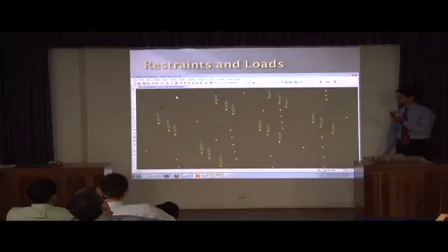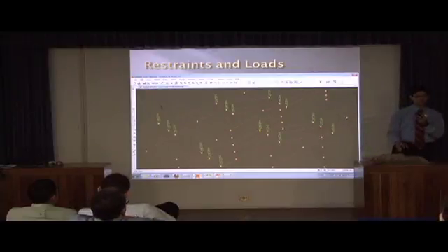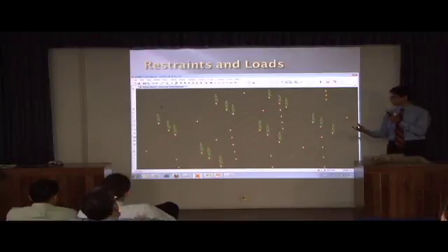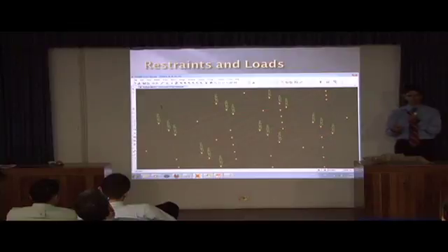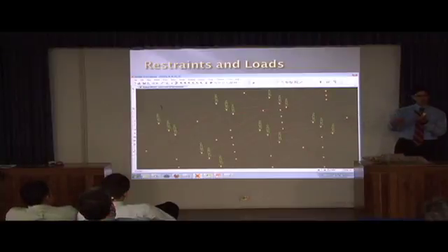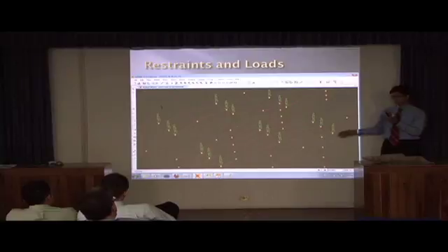Now, referring to loads, we know from reference data the weight of the motor, the engine, and reductor gear. That will be placed in a kind of structure like this. So we have to determine how many joints will be placed in. How to know what part of the weight will be placed on each joint? We have to do a relation, dividing all the weight of the group of engine and reductor gear by the number of joints. So if we have around 2.6 tons for the weight of the whole group of engine and reduction gear, we divide it by 18 joints. We have a value like this: 147.67 kilograms.